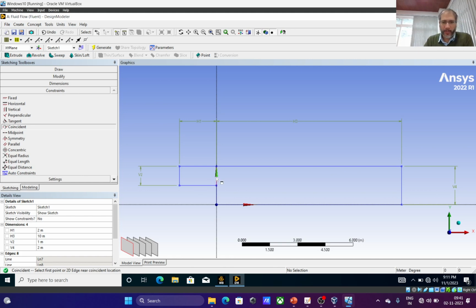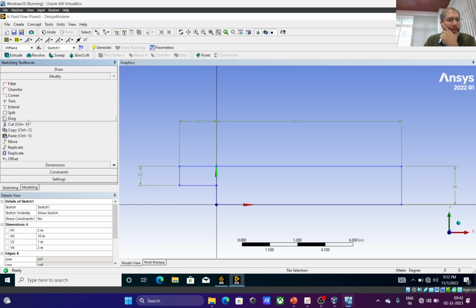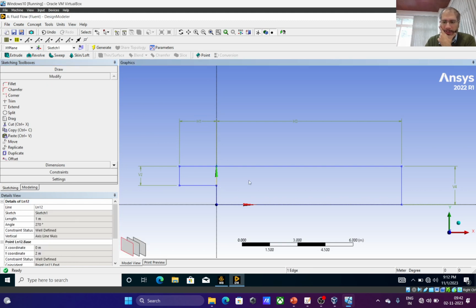Right, next we have to clean it, because you can see that we have connected two rectangles. The right rectangle is a complete line, but we don't want that complete line, so we want this to be a hollow domain. So these lines have to be removed. For that we'll have to modify. So I select this and say delete. That deletes the right edge of the left rectangle, but we still have this long edge that we have to split into two. So we'll do it using trim.